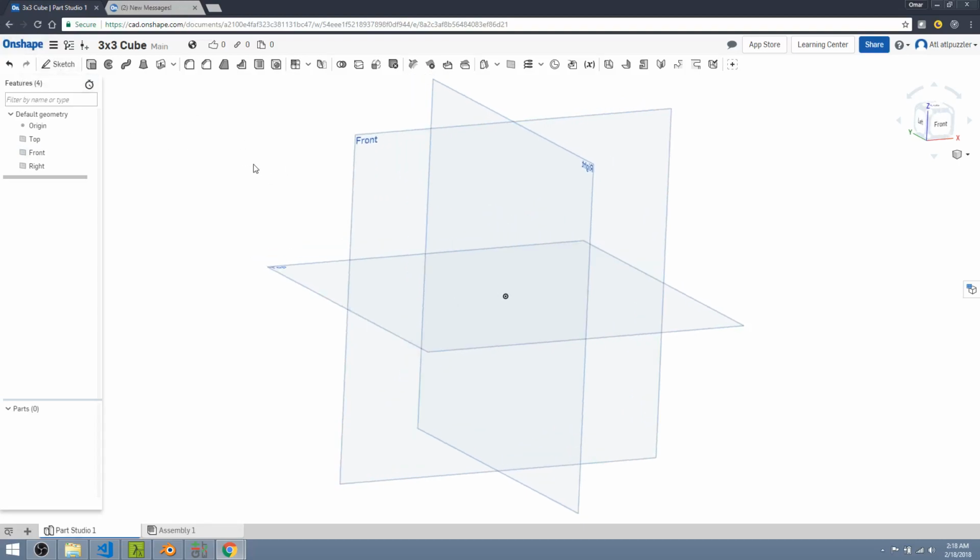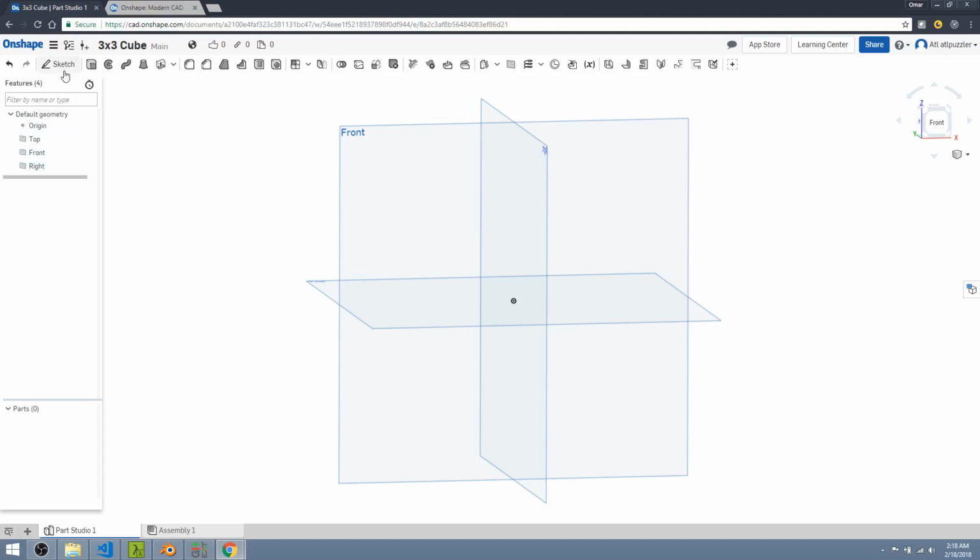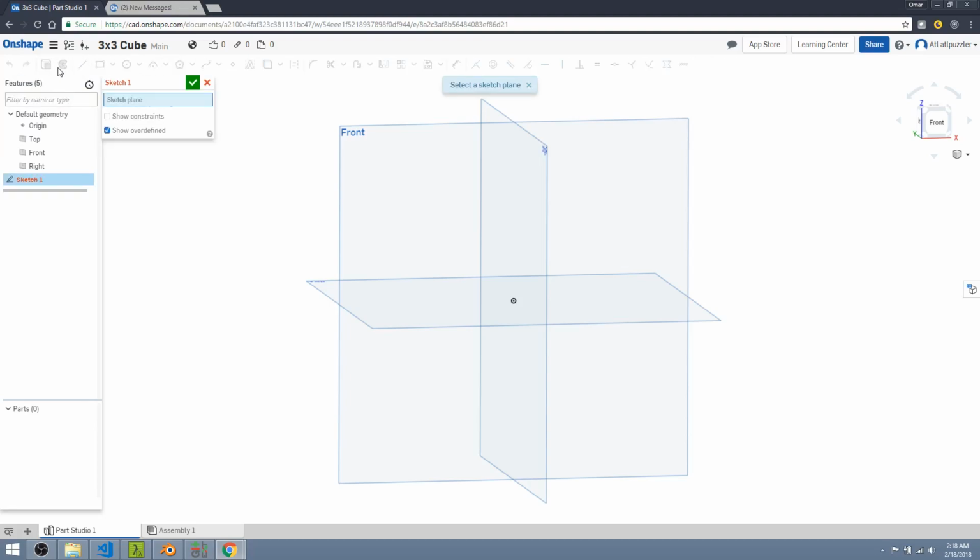One thing I like to do, for doing anything, is to create some axes. And I create the axis by clicking here in the sketch. And all the sketch is, it's a two-dimensional diagram, basically, with lines and circles and other things that we can then take and rotate, or revolve, I mean, and extrude and make 3D solids from it, or surfaces. So anyways, this first one, when you click on the sketch, you can rename it here.